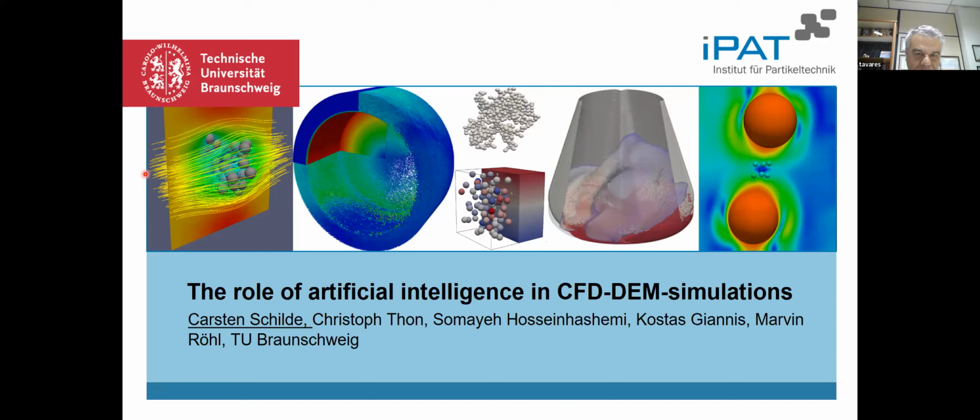But indeed, I think the question when it goes down during wet milling is exactly how much of that material is still being able to be nipped by the grinding media. So yes, I believe there has to be a coupling of more physically meaningful models, and also some back-calculated information or AI type of empirical models to be able to fill the gaps as you go to really fine sizes. So it's just a comment that it's good to see that you're pursuing that, because in my opinion,